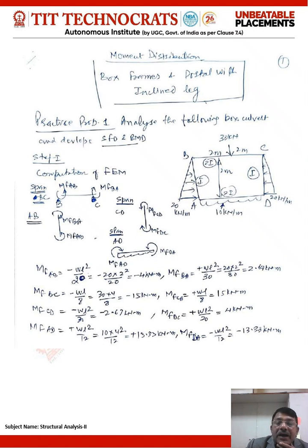You can imagine a small culvert or a small bridge along a roadway, where we make a container of concrete A, B, C, D. So if the load acting upon BC is external in nature, the sides AB and CD will receive a load from the surrounding earth mass.